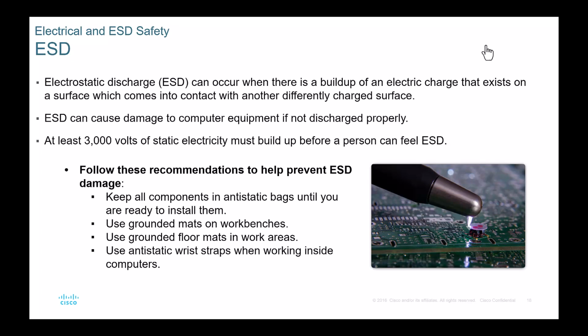So by the time you reach into a computer and you feel that shock, that voltage has already arced and it is already frying components, okay? And that's just for you to feel it. It could be, say, 2,500 volts, and you might not feel it, but when you touch those electronic devices, you could still be causing them harm.